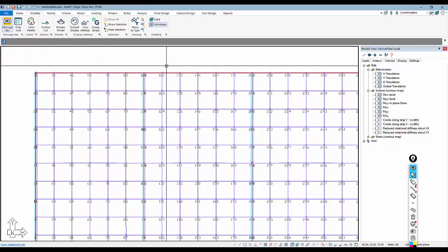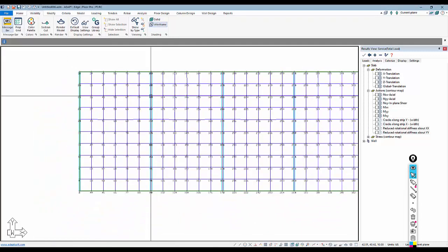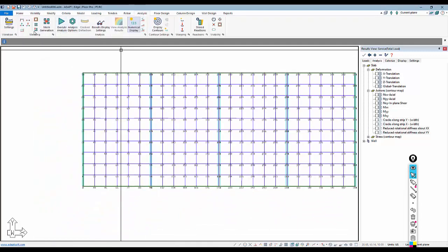Edge 2 there. So one word of caution: if you erase the mesh, you will have to redo this. So make sure that when you want to obtain a solution and results for this type of a run, you mesh it and you retain that mesh.